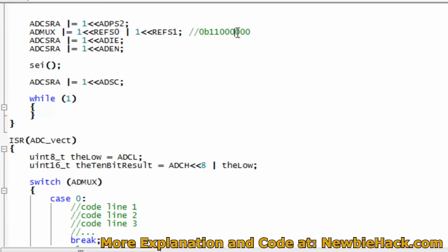So we will have either the bits set like this, or we'll have the bits set like this. This would be channel 0, because the 5 bits here would be all 0, and then these 5 bits has a 1 here, so that just equals channel 1. If it was set like this would be channel 2. But we know that this entire number is not 0, and this entire number is not 1. We have to figure out how to convert this into a hex number, and this is pretty simple actually.